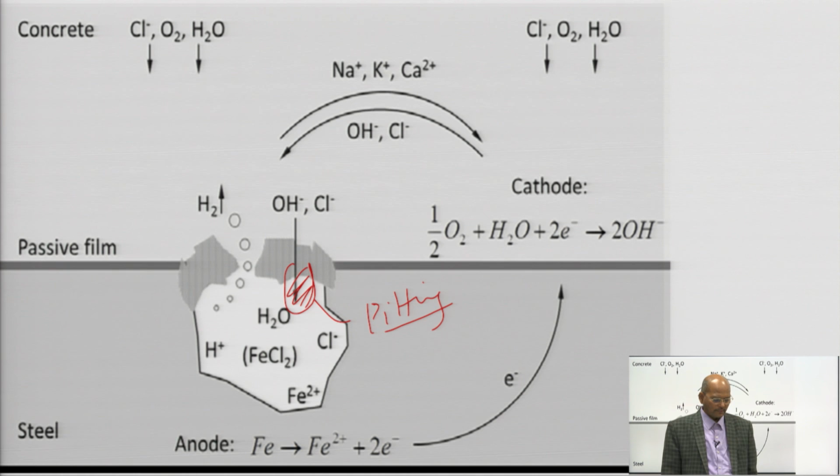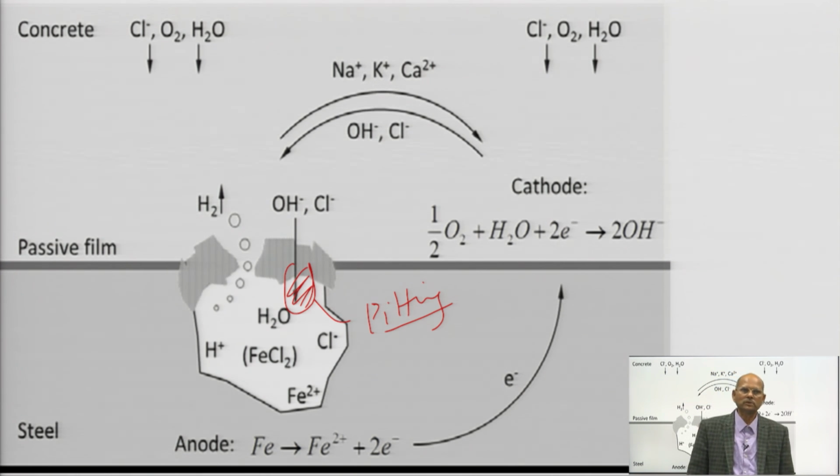Similarly, I have discussed earlier about the Mandovi bridge. They used chloride as an admixture for accelerated setting. So, in due course of time, in about 10 years, that caused pitting effect, and finally that bridge collapsed. That Mandovi bridge collapsed in running condition in 1986, and many people died in that accident. So, that was a very small mistake.